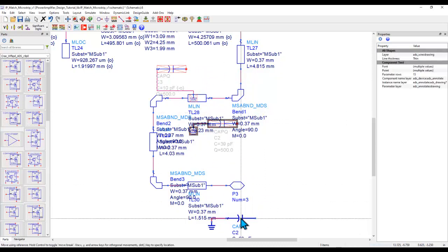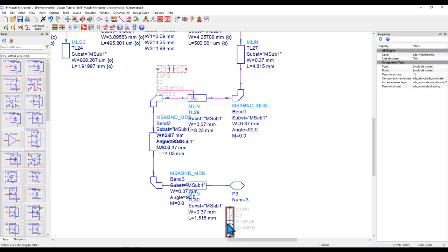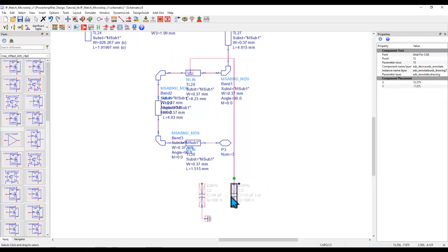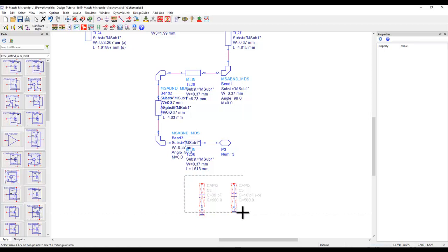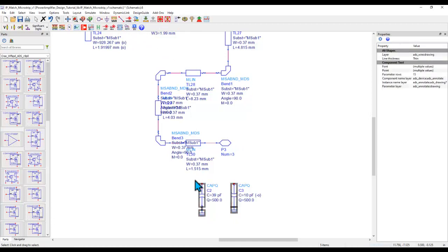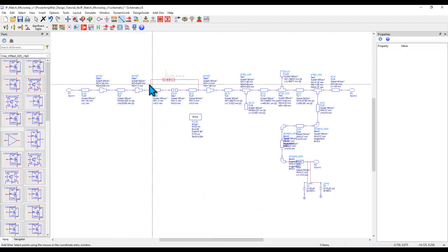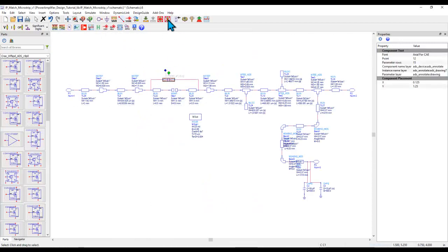So these capacitors can be placed again at the end of this overall transmission line, and now I can make that connection here along with the rest of the line, so that when you activate these components for your circuit simulation, you have the right result. Sometimes using this method, be careful if you end up simulating this circuit with these capacitors disabled, especially the series ones, then you might have an open circuit issue. So make sure you enable that after you have done the layout generation.